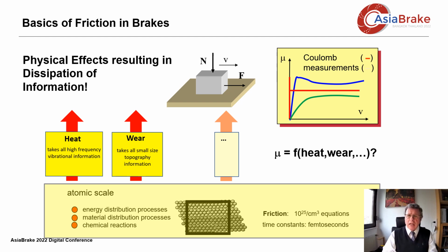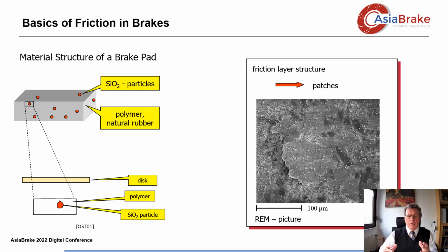Another mechanism is wear itself. Microscopic or even atomic surface details change at any time. But wear sums up all these geometrical microscopic changes and can be described with a few macroscopic variables. With this in mind, a microscopic friction law should be at least a function of temperature and wear. Before I talk about friction laws, please let us have a closer look at brake friction.